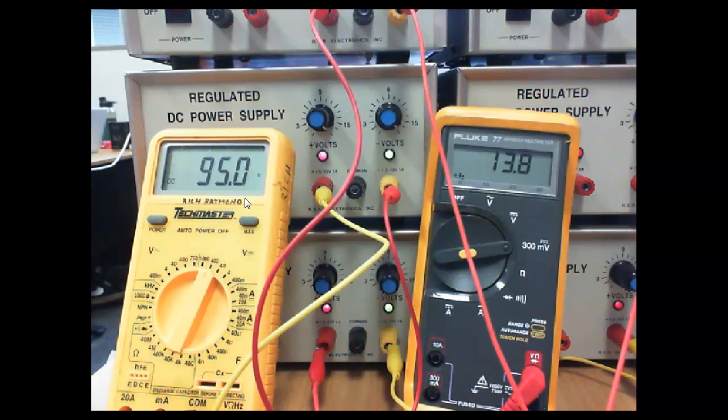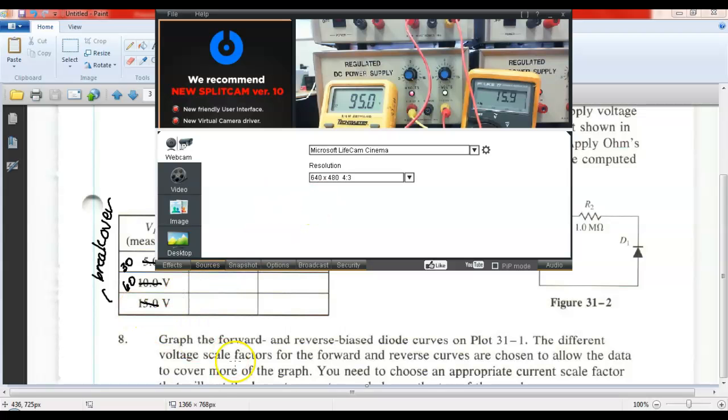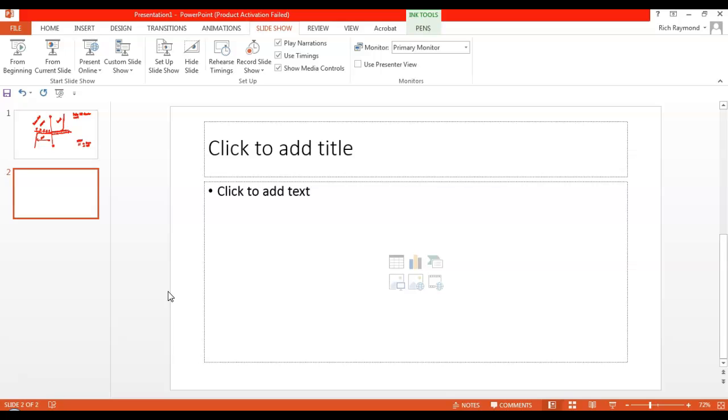When you did the meter certification, one thing you did was measure the resistance of the voltmeter, and it measured around 11 mega ohms. We usually assume for your new meters it's around 10 mega ohm. So what was happening is we were using a 10 mega ohm resistor because we really wanted to protect our resistor.